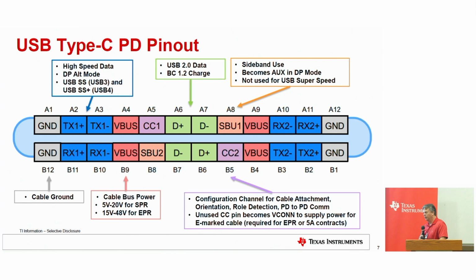Both sides are set to handle the over voltage or under voltage condition discretely themselves, same with current. So if on the far end device you have something sitting out there with a 2 meter cable and you're dropping too much across and you go below the minimum threshold, it'll open its power path for safety reasons. Okay, thank you. That itself doesn't have anything to do with the chip inside the cable. That's just the IR drop, the voltage drop. Yeah, I got it. Thanks. No, thank you.